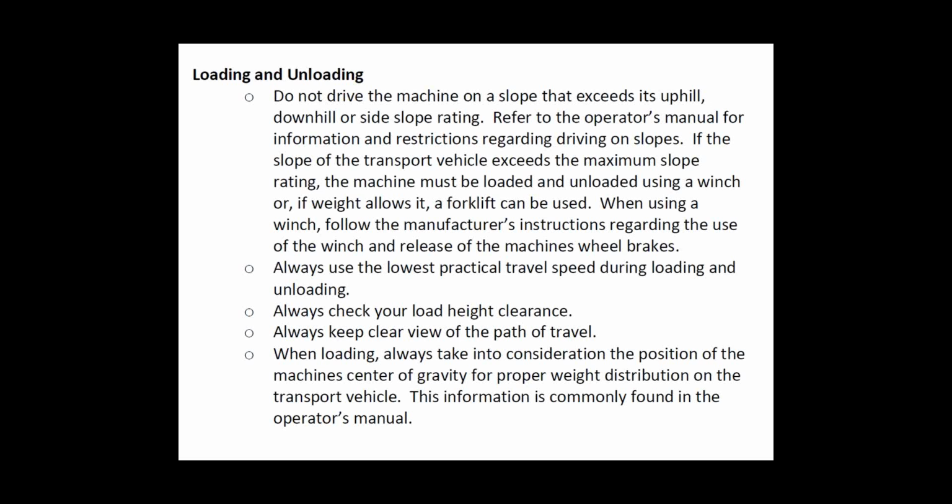Once we get the machine on the truck, we want to ensure that the height of our transport hasn't exceeded the height of the allowed requirement. It's always a good idea to have reminders in and out of your facilities to make sure that you haven't exceeded the transport height. Always take the machine's center of gravity and the distribution of the load into consideration. And this information is commonly found in the operations manual. We never want to use the machine elevated on a transport vehicle.